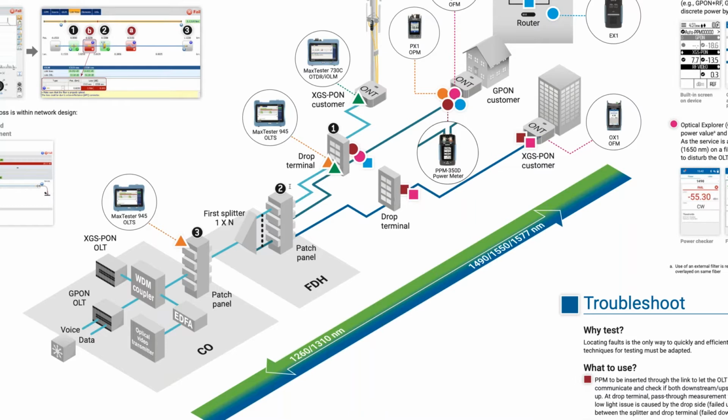What I wanted to demonstrate for you guys is the difference between how an OTDR operates, the OTDR software, and then the IOLM software, especially in a PON environment. And then also we'll take a look at the OX1 and some of the use cases there.